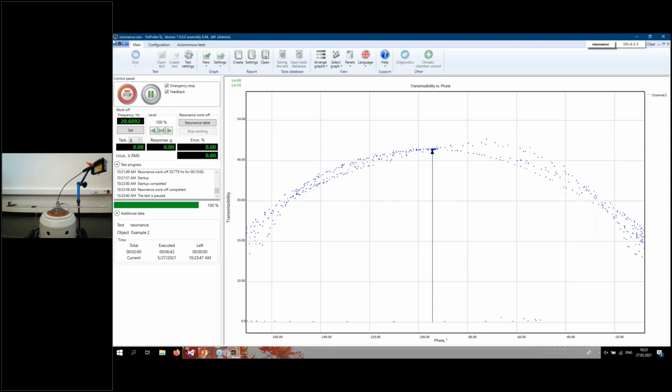The main difference between a fatigue test and a regular resonance search is that you don't need to place your sensor on your object during a fatigue test. If you search for resonances, for example, on a turbine blade, the accelerometer will influence its mass and also its resonance frequencies. So in that case we use a laser vibrometer. That's the main difference between fatigue and sine resonance search.